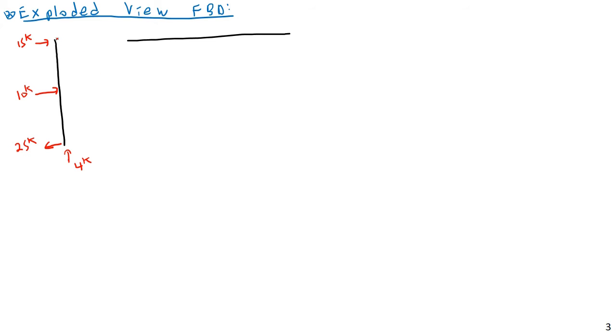Then I'm going to have a BX force, a BY force, and an MA. I could have assumed these going either direction, although I just decided to be a little bit smart on this, starting on this end, because I know just looking at this that BY is going to have to be going down. If we look at our equilibrium here, the only vertical forces on this are this 4 kip force and this BY force. So in fact, I can go ahead and say BY is going to be equal to 4 kips as well.